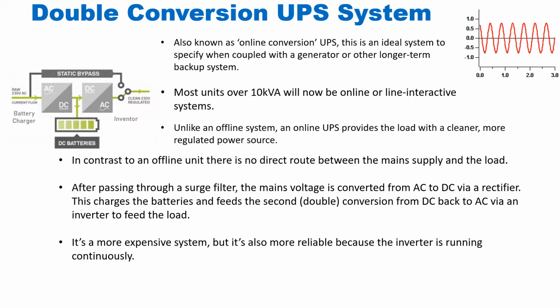It is informed through a link with the UPS that it is now not running on utility power, but purely on UPS power. And after 30 minutes, the UPS is going to shut down. So the software on the server will start a countdown as it comes closer to the 30 minute mark. I'm just giving you 30 minutes as an example. It could be different for different UPSs.